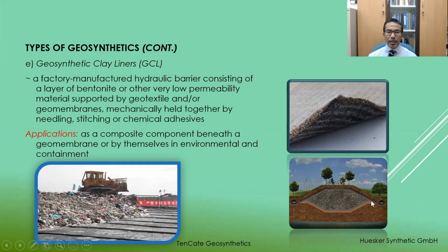sheets. Geosynthetic clay liners are normally placed at the bottom of this landfill facility to form the liner system, because the geosynthetic materials will provide strength, whereas the clay material, which is sandwiched between these two geosynthetic sheets, provides the impermeable layer. This clay material will expand and become impermeable when in contact with liquid or water.